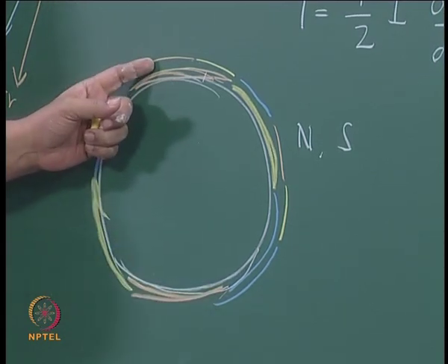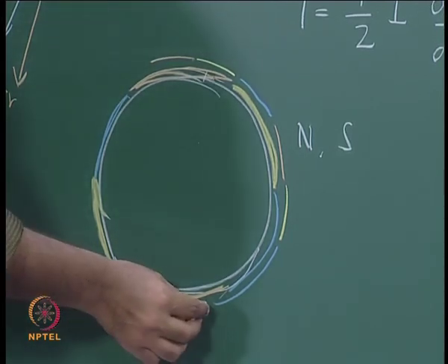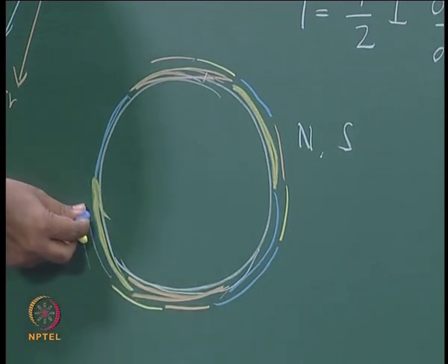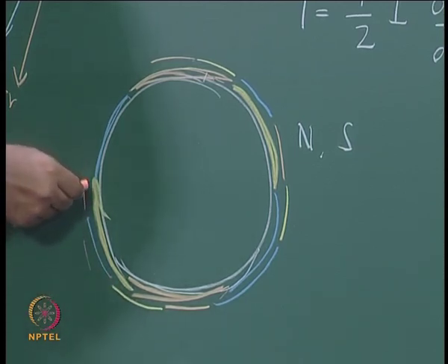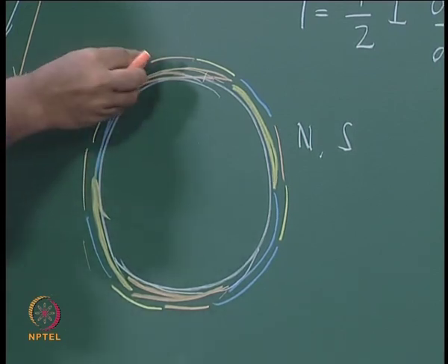From the start of this to the end of this will be one cycle of the MMF waveform, and you want to have one more cycle of the MMF waveform. So, you would have R again and then Y again, then B and then R, Y and B.